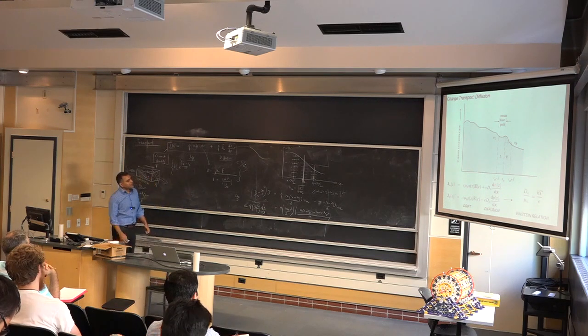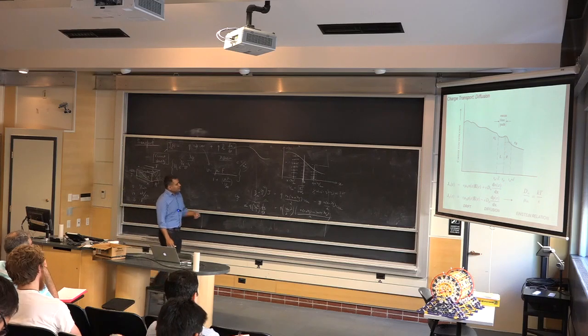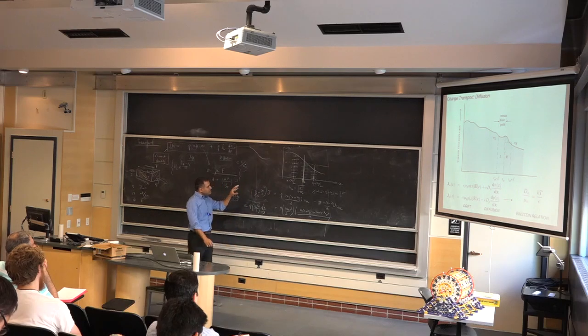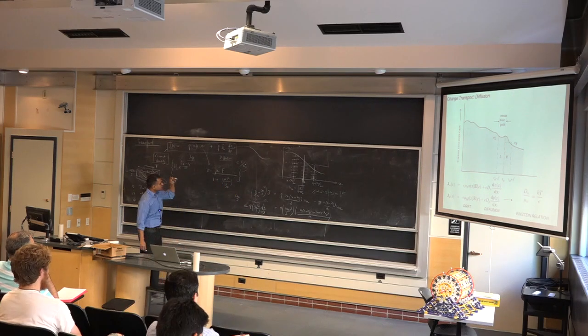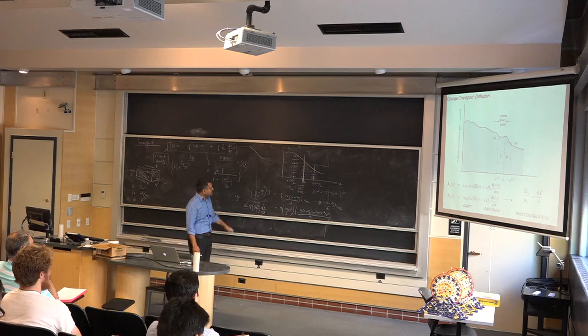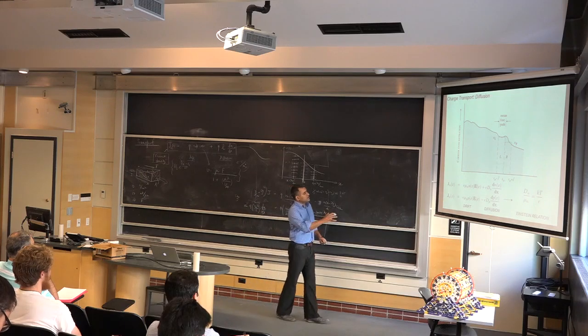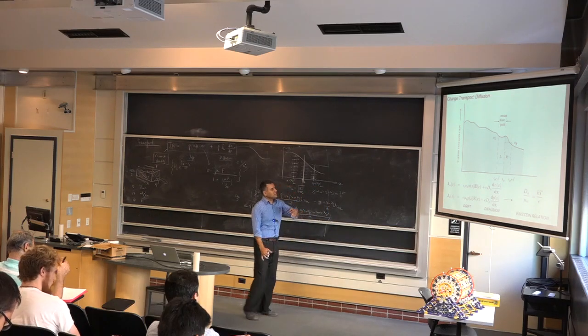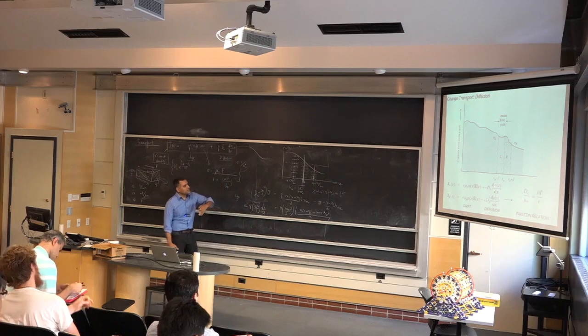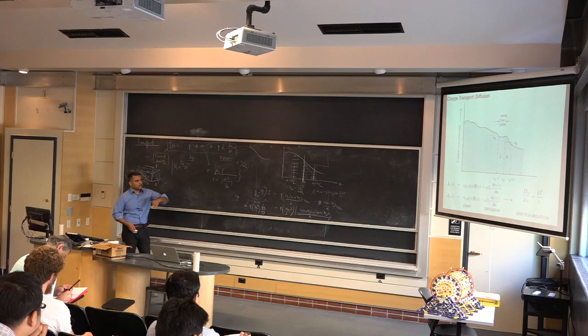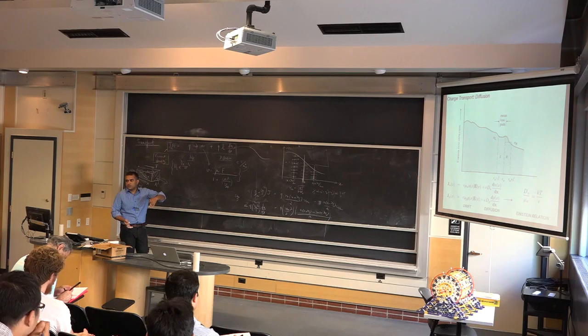And it might seem here that the only way you can get this sort of diffusion is by heat. And that is true if you have semiconductors that are not doped very heavily. In fact, by this relation, even if you create a gradient, as you can see, if I just create a gradient and I leave the material and don't apply a field, there will be some current flowing, but the current cannot flow forever. I mean, there's no external voltage, right?